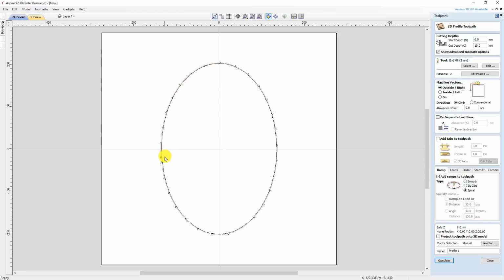Then it starts on its second round and it'll make its way from 5 millimeters down to 10 millimeters for the second pass, and now it has to do one final pass to clear up everything at 10 millimeters. So a spiral pass requires an extra rotation or an extra cut around the material to finish off. The better option here is the smooth.